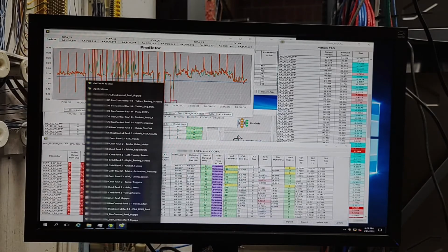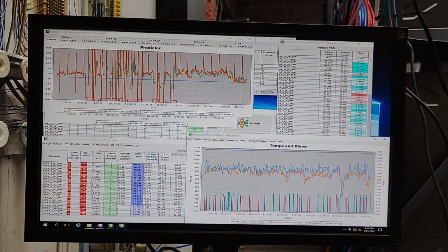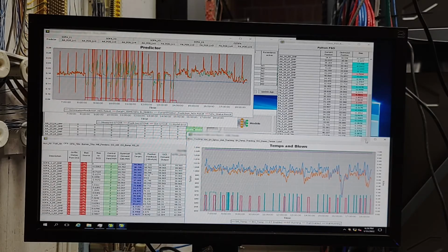The sootblowing application operates the same way. You can see here I can monitor each sootblower activation that the unit or that the KSB system engages by each one of these little spikes. Each one identifies a different type of blower, and I can see how each blow impacts final steam temperatures here. All of this is developed again in response to unit circumstances, and the knowledge-based soot-blowing system is exactly that. It's a knowledge-based, rule-activated, and governed system. We have a lot of success with generalizability and consistent performance.